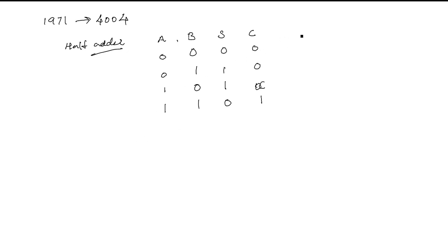For a simple circuit to illustrate the operation, we have an XOR gate here. This is the symbol of an XOR gate, with no bubble, where A and B are inputs and here is our sum. And we need the carry by means of an AND gate, with the same inputs A and B, and we will get a carry here.